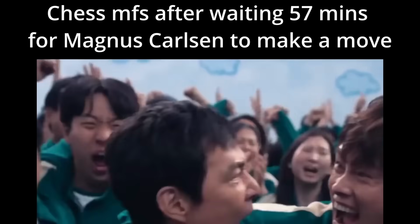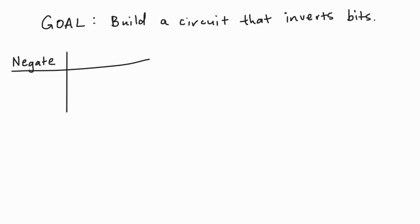I'll make another more technical video, but for now, just know that to get a negative binary number, you have to invert all the bits in the number and then add 1 to it. So to get A minus B, we need to add A to B inverted, then add 1 to the final answer. So it'd benefit us if we could build a circuit that could invert a number whenever we wanted it to. Let's drop a truth table of what we want.